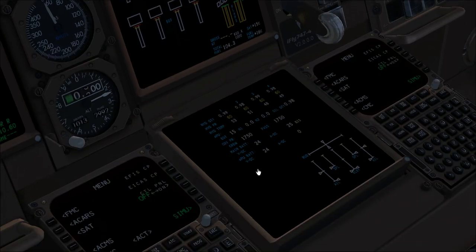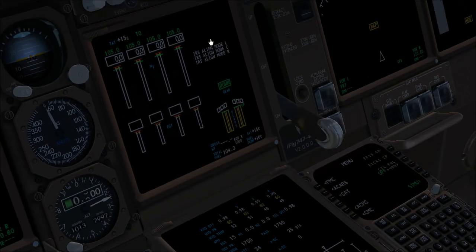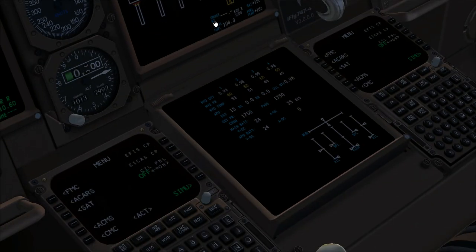In this case, yes, we don't have any yellow or red message here, because when you start up the aircraft, all the messages are suppressed until the startup. This is a way to eliminate messages that would otherwise be there. For example, engine oil pressure is probably one message that should be there because the engine is off, but in this case it's suppressed until the engine starts up, to eliminate some distraction for the crew looking at the screens.